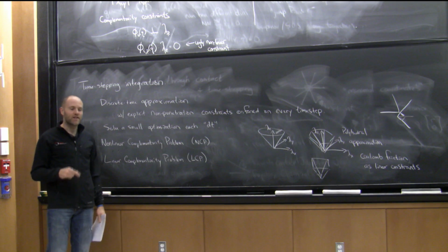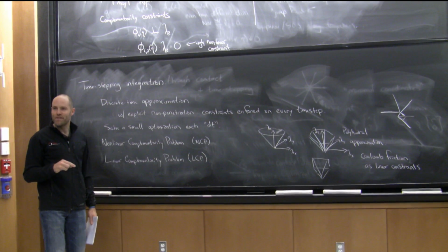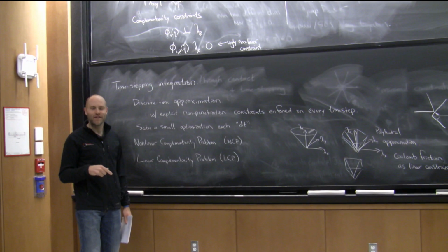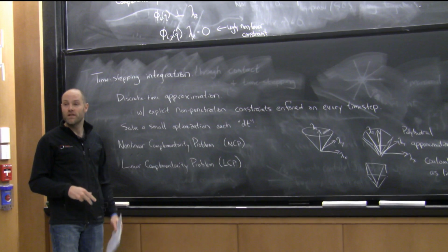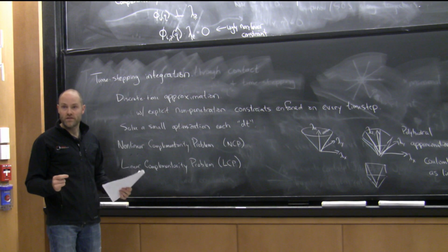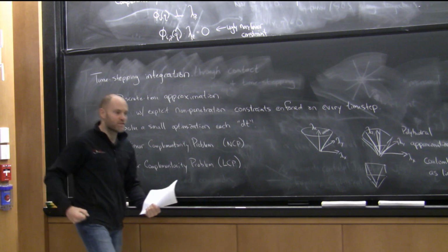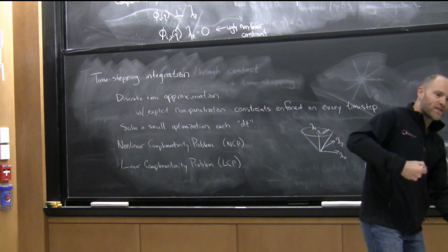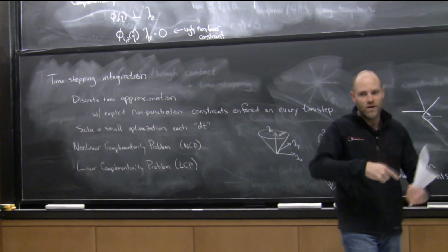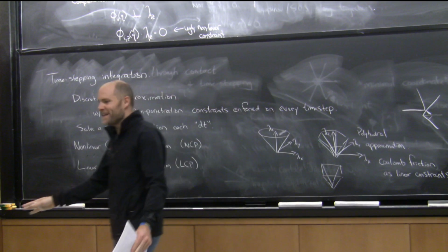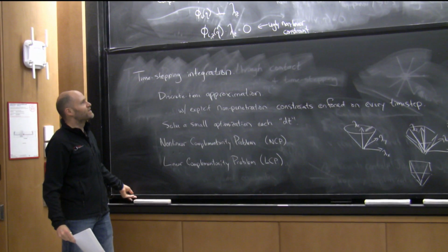In the Virtual Robotics Challenge for Atlas, the top speed of our walking algorithm in simulation was limited by the LCP solver again, because even the rigid body equations in Gazebo, at least when Gazebo is using ODE as its backend, are written in maximal coordinates. So joints are only held together by contact forces. And what happened is if you started your massive robot moving fast enough, then the joints started separating and going apart. At some point it got ridiculous, and our kinematics were wrong. We'd fall over. We said, let's not spend time fixing that, and actually the real robot turned out to be easier to control than the simulator at some point.